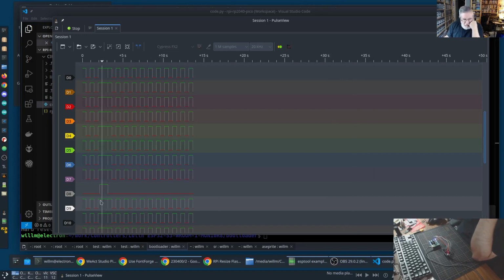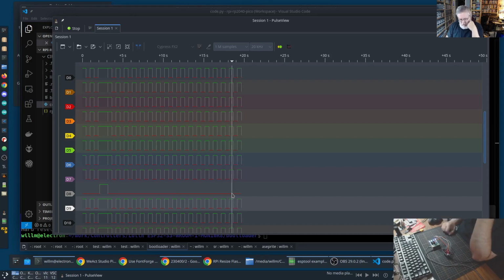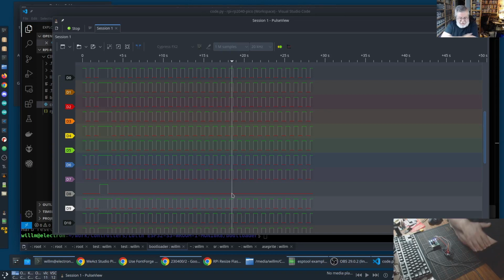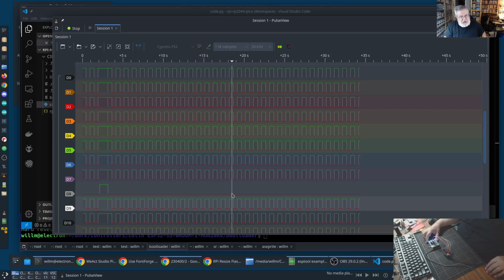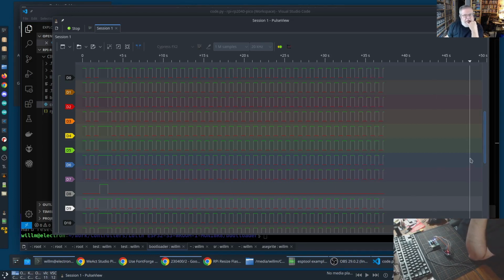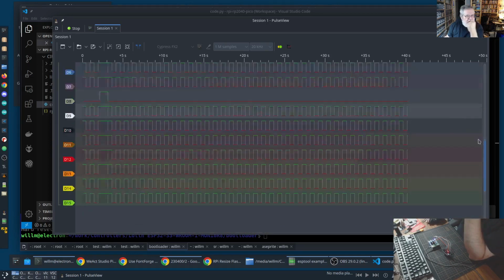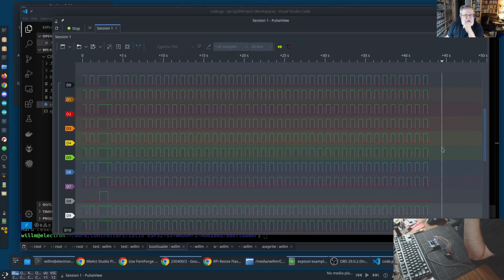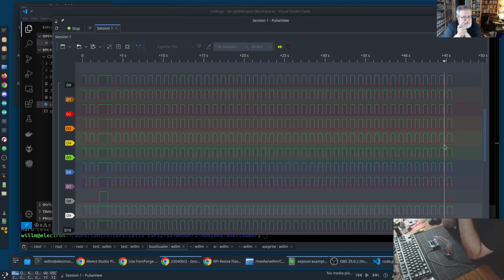And you can see I got the wiring right this time. Number 8, which I turned off, it's not showing any. Every time the thing rises, the light goes on. Every time it falls, the light goes off on the LEDs. So I can actually detect all the pin states through the logic analyzer. Now, for some reason, it only goes up to 16 channels in here, which is okay. Doesn't really matter. It would be nice if it could actually do all the pins. But after 16 anyway on this breakout board, it gets a little jumpy.